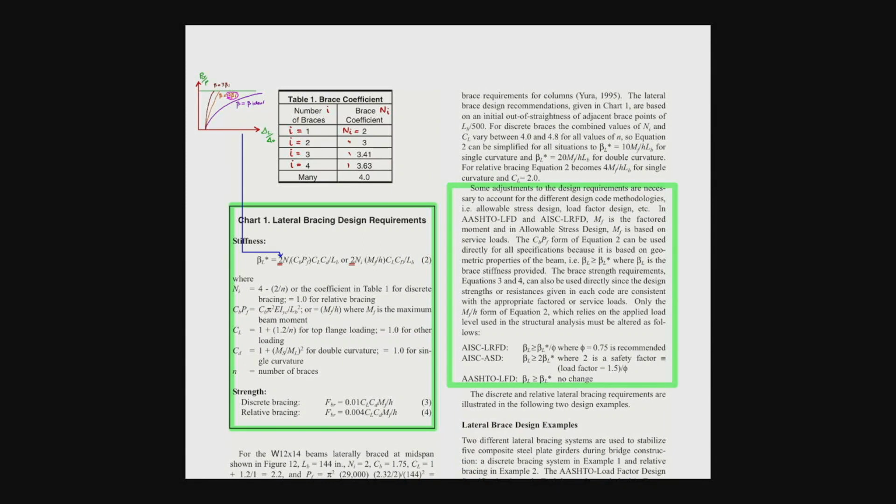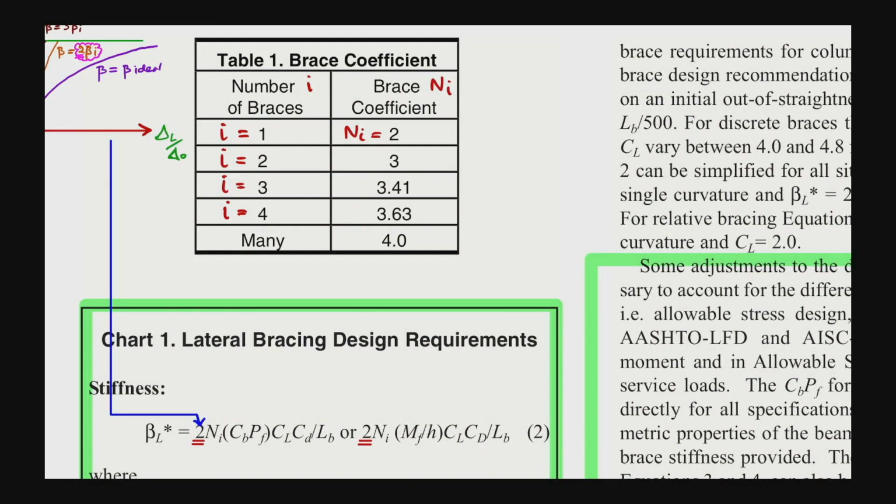2 times, twice as much as the required ideal stiffness, the calculated ideal stiffness. So with the initial imperfections and the considerations of the bracing force, you are still at the optimal point where the brace stiffness is not too high, not too expensive, and the behavior is good.